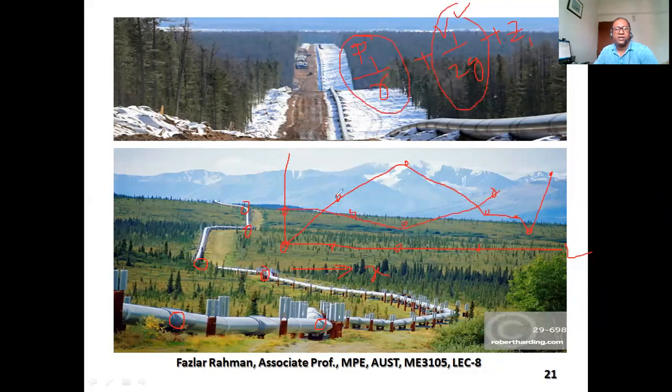You see P by gamma, say right over here is too high, then it is again increasing, then again decreasing, and just show him the graph. So he can observe the pattern of your pipeline from one region to another, where pressure is too high, where velocity is too high, where the datum is extremely high or extremely low. Okay, so this is the application.